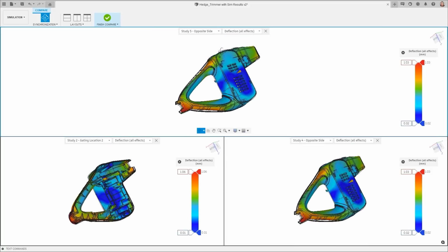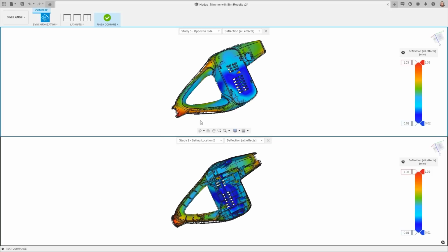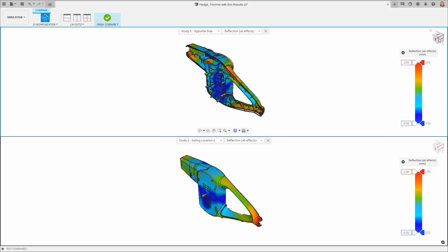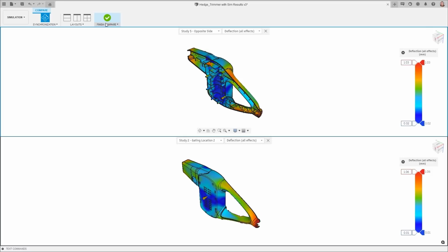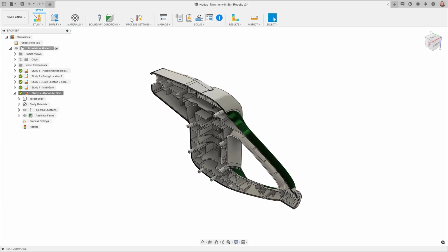Now, it's important to note that there are many different ways to modify an injection molding process for manufacturing. Because of this, the tech preview is currently limited to analyzing accurate results for traditional injection molding of individual parts only. It does not yet support more complex molding sequences, nor allow for analyzing mold design features such as feed systems, cooling systems, or multi-cavity designs.